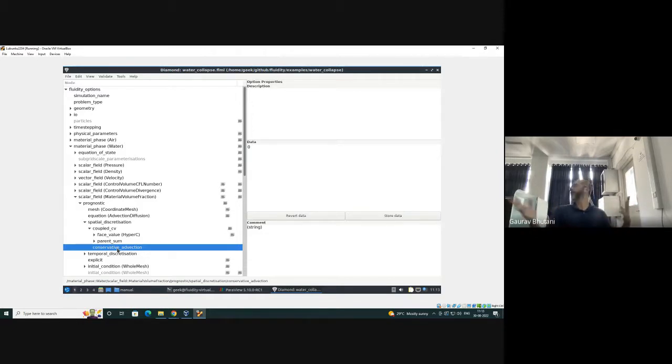So it uses some method because earlier the mesh node was somewhere else. Now the mesh node is somewhere else. So how do you find the information at the new mesh node given old mesh nodes? You have to interpolate between triangles. It uses some method for that.